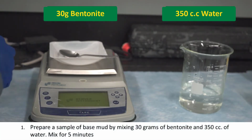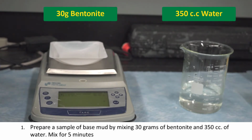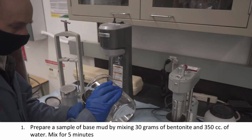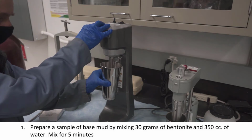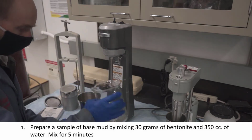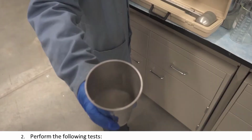To begin, prepare a base mud sample with 30 grams of bentonite and 350 cc's of water. As it was done in previous experiments, do not mix all of the bentonite and all of the water at once. Mix for 5 minutes using the mud mixer.